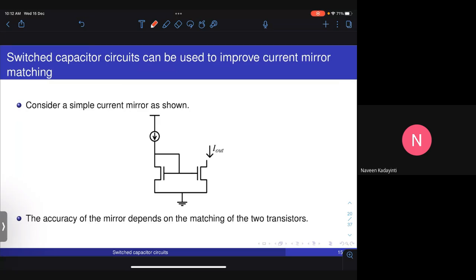What happens here is, if these two transistors are matched, this current I will generate a VGS here, and then I out will be (k/2)(VGS minus VTH) the whole square. If your transistors have high output impedance, then this 1 plus lambda VDS can be ignored.